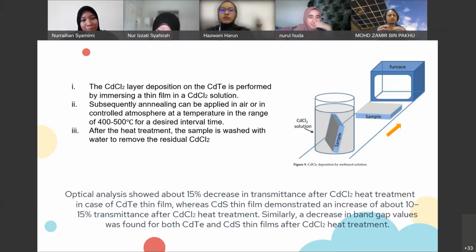On the other hand, if your grains are bigger, then you'll have fewer boundaries over the same area, so you won't hit the border. Therefore the carriers will experience less recombination, and that will be good for the device, especially in terms of the VOC, the open circuit voltage.